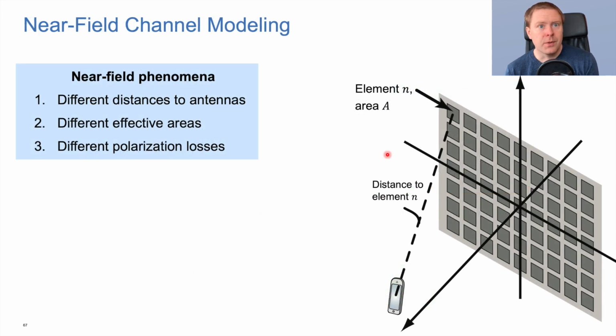What I described so far is how to model the channels for the surfaces when we are in the far field. But then I was also saying that one of the key interesting things that could happen when you have a big surface is that you can also have near field behaviors. And a particularly interesting thing was happening when we were so close to the surface that we can actually focus energy in small regions and not create beams.